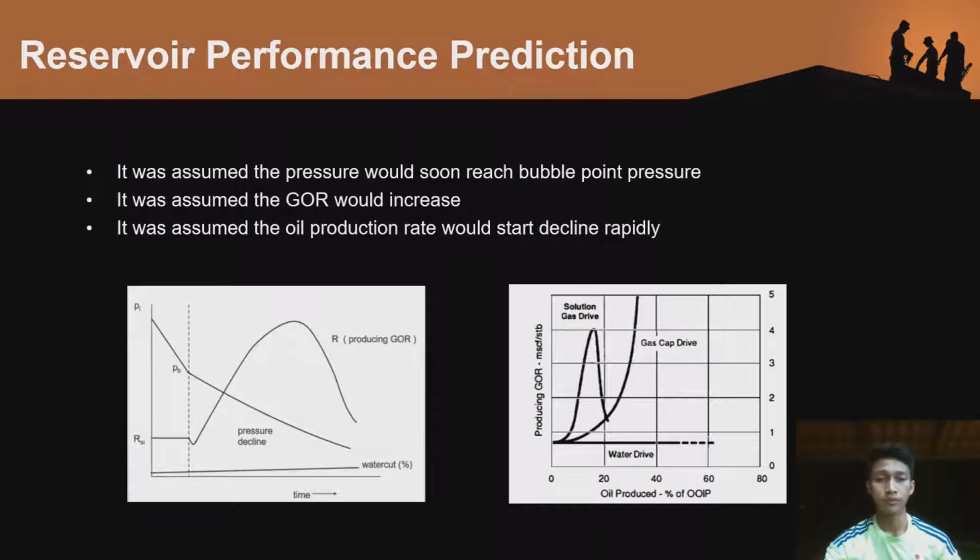For performance prediction, the reservoir was assumed to behave according to a solution gas drive, in which the GOR would increase. This was assumed because in solution gas drive, there is no initial gas cap or underlying aquifer. Oil is produced by the driving force due to the expansion of oil and connate water, plus any compaction drive. Here, since it is indicated that the contribution to drive energy from compaction and connate water is small, oil compressibility initially dominates the drive energy.